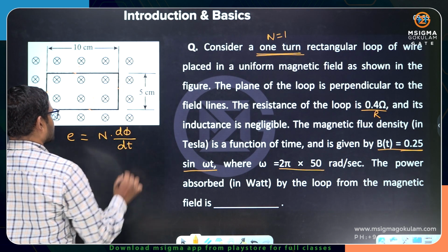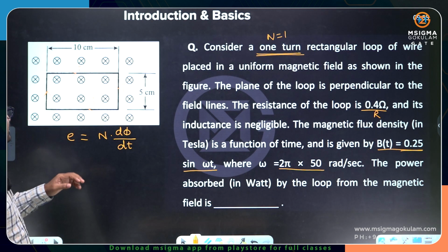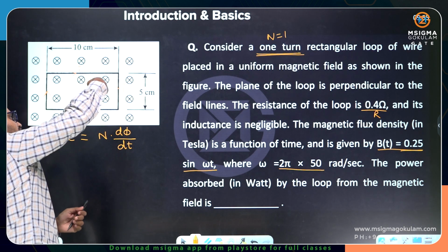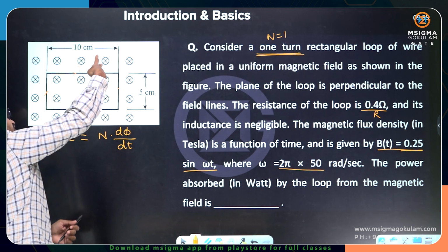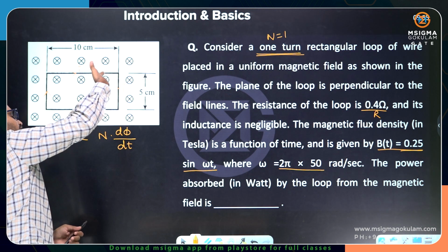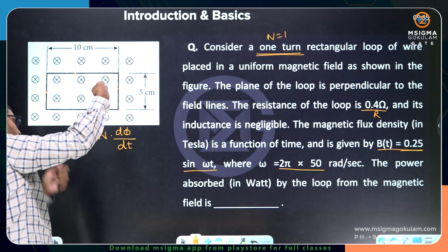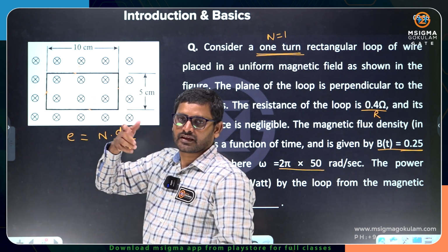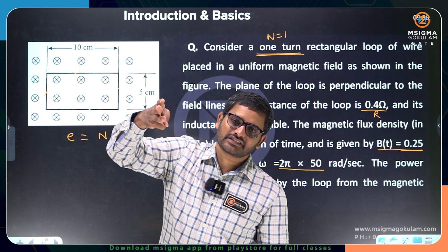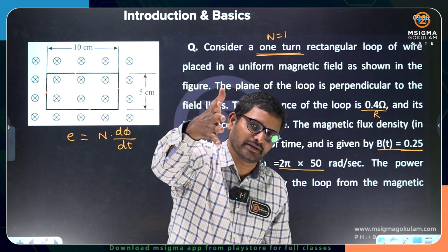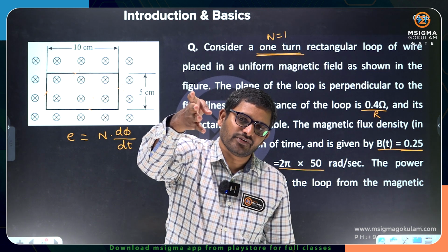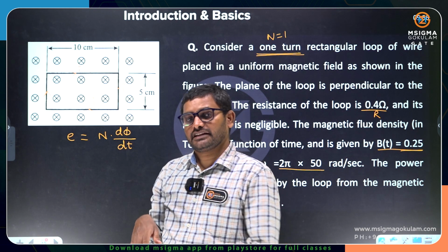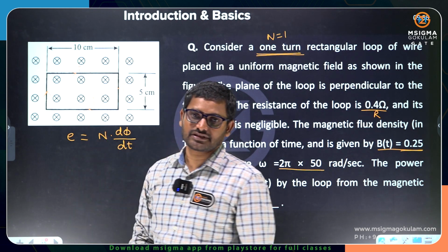The rate of change of flux linkages will induce an EMF. How is it changing? Though it is perpendicular, there are like 1 flux line, 2, 3, 4 and 5 flux lines, all perpendicular to the plane, and again later 5, 4, 3, 2, 1 and 0. So they are perpendicular and changing with respect to time, so EMF definitely is induced.